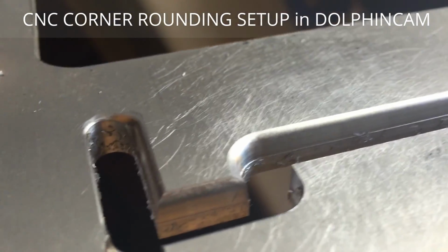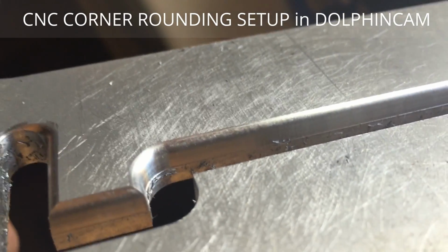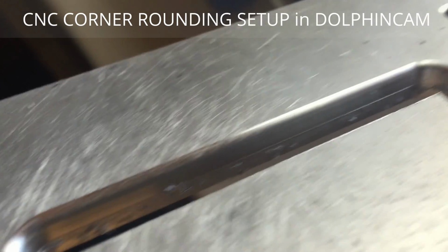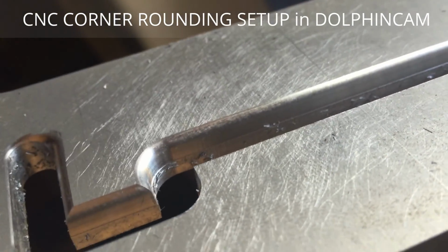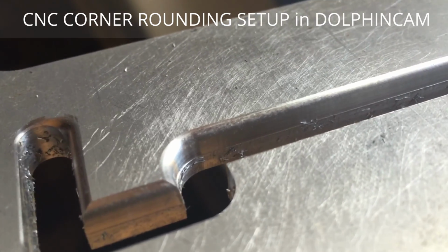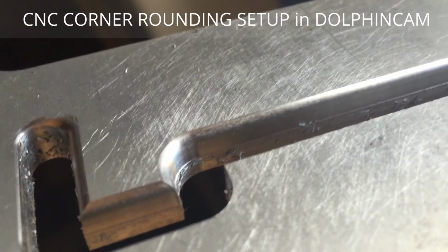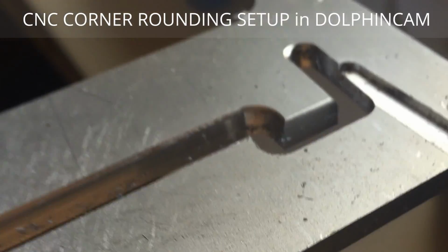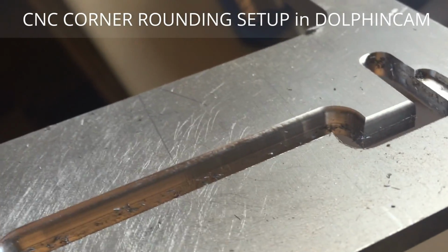On the inside edge, the 0.5 times diameter, looks like I went in a little too close. So I'll back that off. Instead of 0.09, I will make that 0.08, 3 or 4. So from 0.09 to 0.0845 maybe. And that'll take care of that. She came out really nice. I think that'll be a really nice finish for this once it's done.